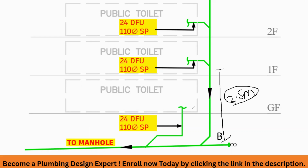So the best practice is not to connect the ground floor fixtures to the stack. Give a straight height without connecting any branch to this pipe. The minimum value is 2.5 meters, and for high-rise buildings, it increases. It goes to 5 meters also.